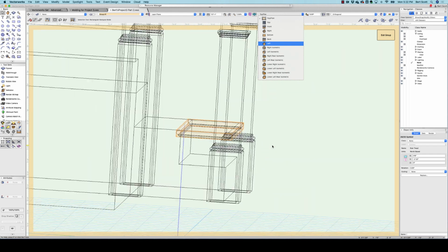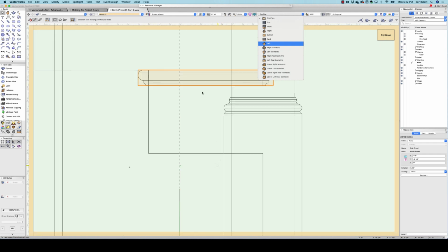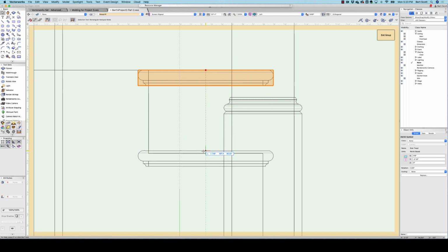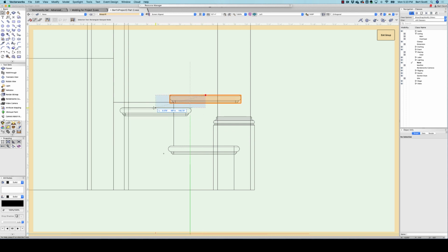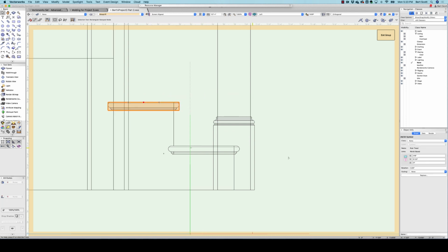And then if I go into left view, I'll see that in order to make that happen, I need to pull it down so that it corresponds to the top of the staircase, so that the tread is at the top of the original tread, if that makes sense. So then I'm going to duplicate this and put the center of it there at the center of my next step.